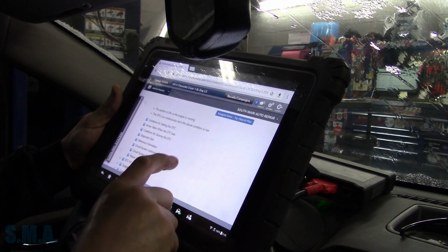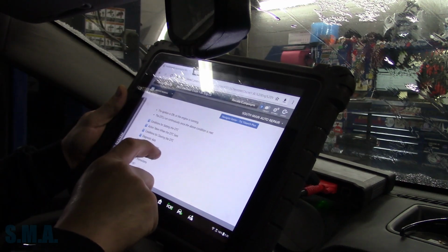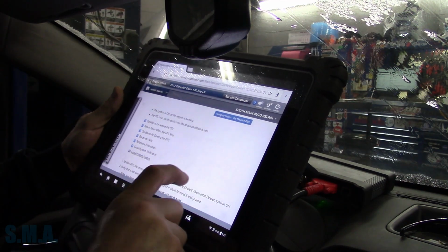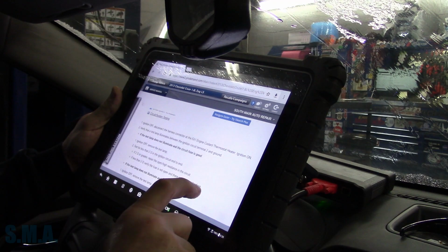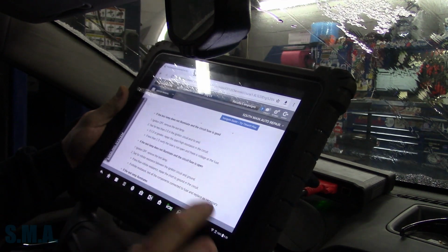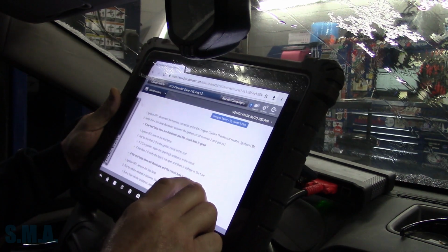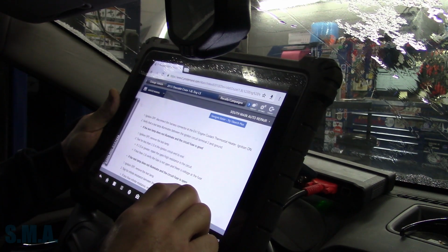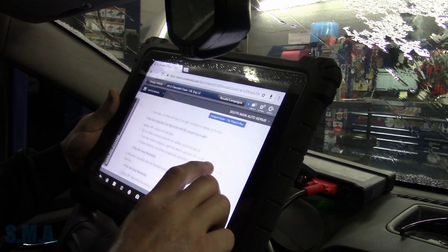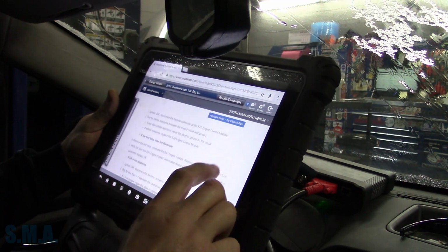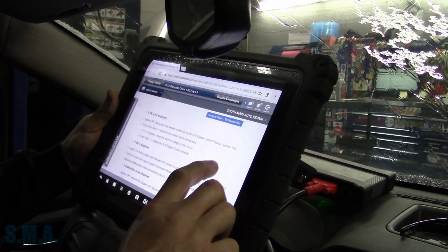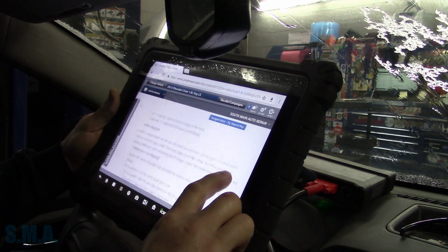So that's that. We can find sometimes circuit tests to see what kind of resistance this heater should be, and just see if it's open. It probably is. Let's see here. See if I can find that for us in service data somewhere. That's usually where they hide it, if they have it as a test.